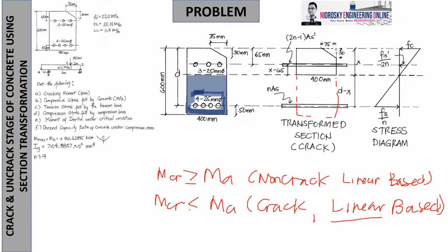Non-functional. So what is this long area that you see? That is the representation of the modular ratio. Because this is steel, I will mark it red. We are converting the stronger material into a weaker material to make our analysis homogeneous. Under tension first, this is the equivalent, and that is N times AS, modular ratio times the area of the steel, total steel area, under tension only.